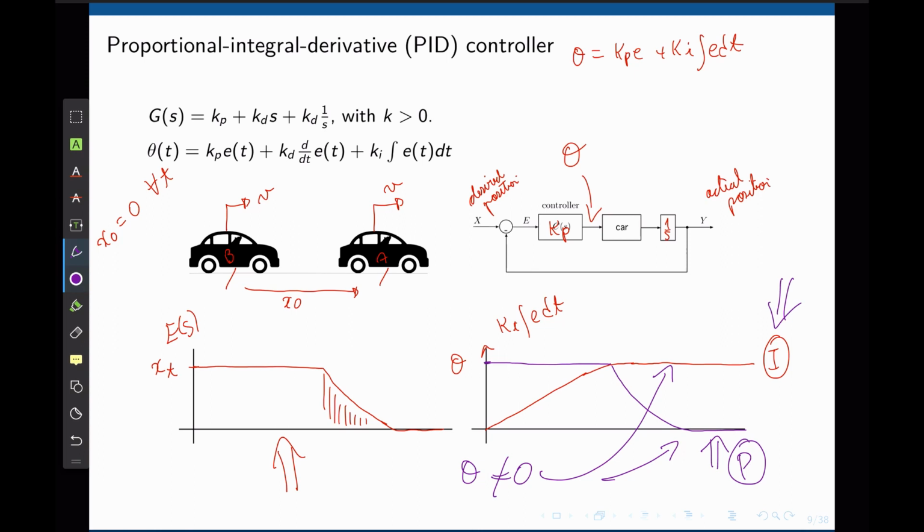go side by side. Notice that the integral controller will always have an effect on the system so long as the error is non-zero. Adding an integral controller means that the steady state error always goes to 0, because the integral component will keep integrating the error and accumulating some control effort, slowly changing the control effort up to the point where the error becomes 0, and then the integral component simply becomes constant.